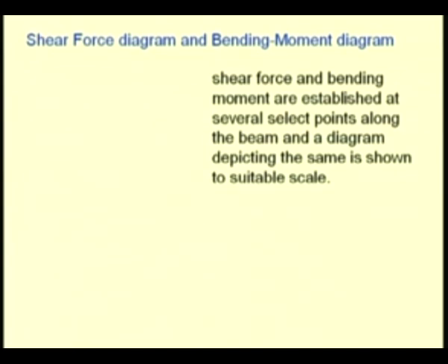We have the shear force diagram and the bending moment diagram depicting the shear forces and the bending moment, which are the predominant internal forces in a beam, along the entire length of the beam for a particular loading condition and supports.